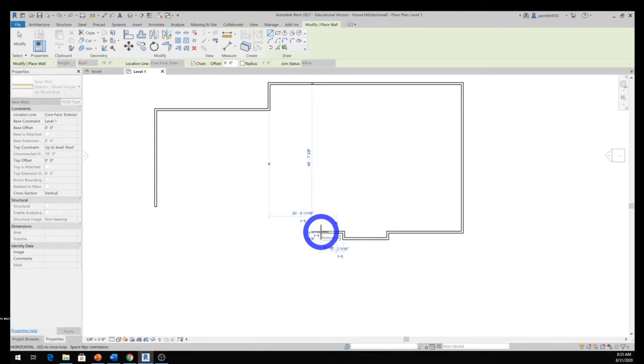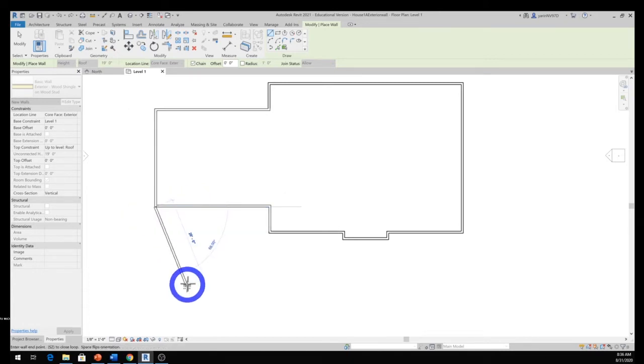Enter. It should be lined up by, whoops, didn't do it. Let me undo here. Something went wrong, so if you make a mistake like that, you can go ahead, click undo, and then start over again from here and type 23. Enter. Then go back up again 8 feet. Enter, and it should be lined up with this wall right here. Click, and that's the escape for now.